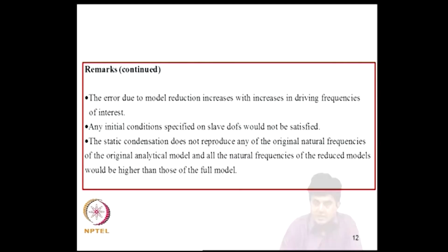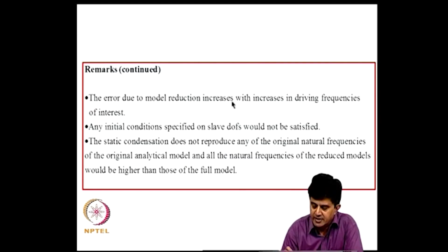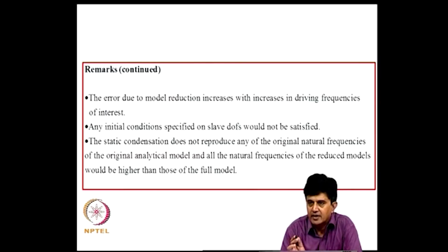Now, it is clear that the error due to model reduction increases with increases in driving frequencies of interest. That is because with increase in driving frequencies the kinetic energy goes on increasing, and we can't ignore mass. A mass which is small at low frequency will contribute significantly to kinetic energy at a higher frequency. Therefore, the assumption will start breaking down.